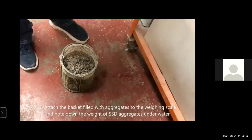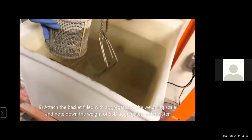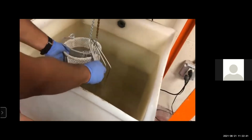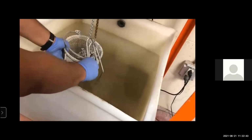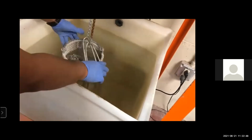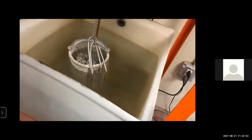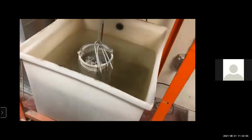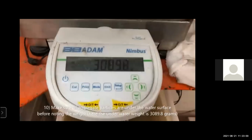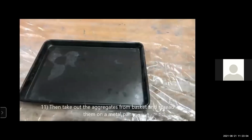So attach the basket filled with aggregate to a weighing scale and note down the weight of the SSD aggregate under water. So here we attach the basket and immerse this basket in the water bucket or water tub. So here you see our basket is immersed in the water tub. Make sure all aggregate particles are under the water surface before noting the weight.